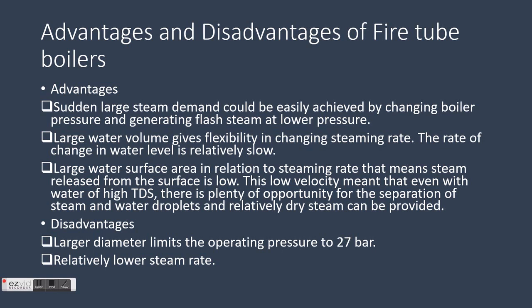Quickly go through it. Advantages are that a sudden large steam demand can be easily achieved. Then, large water volume gives flexibility in changing steaming rate. The rate of change in water level is relatively slow. Then, large water surface area in relation to steaming rate leads to a number of advantages. Disadvantages are: larger diameter limits the operating pressure to 27 bar, and a relatively lower steam rate.